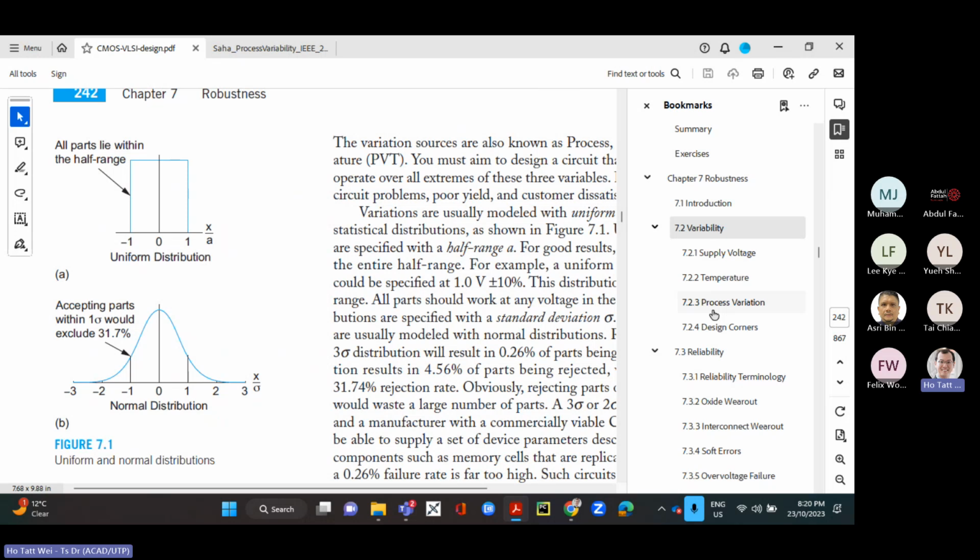Okay, so process variations, that is when I try to make something according to a recipe, according to a design, my imprecision, the inability of my fabrication process to make exactly the same thing, is going to cause variations between each chip that I make. Besides that, there is how I operate that VLSI IC, right? So I've already created it, fabricated it, I cut it up, I put the wires, wire bond it, and then I'm running it, right?